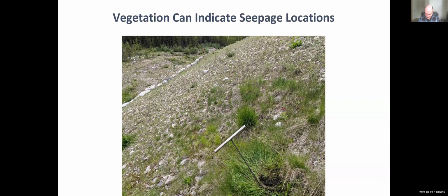And I think this is my last, or almost my last example. So here's the downstream face of a dam. And there's a few little shrubs growing here. They're not of any substantive size at this point because they're smaller than the thumb. They can just leave them be. But you can see where we're sort of standing here, and where this probe is pushed into the embankment, there's water sitting right there.